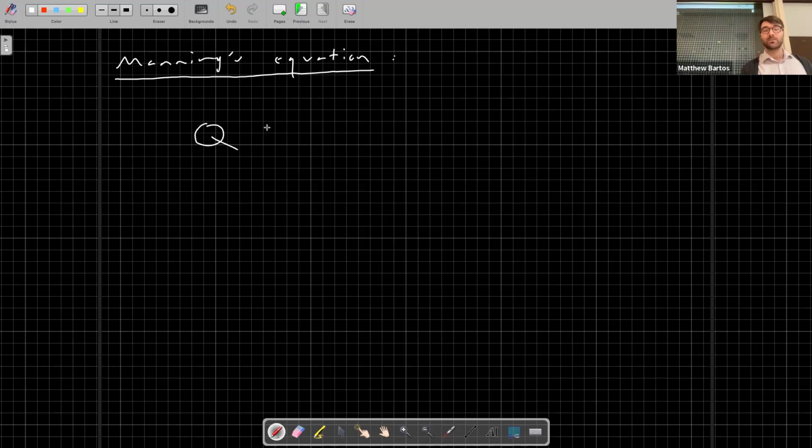So if we take that value for C and plug it back into the first equation on the previous slide, we will get phi CM divided by n, as in November, times the cross-sectional area times the hydraulic radius to the 2/3 power times the friction slope to the 1/2 power.